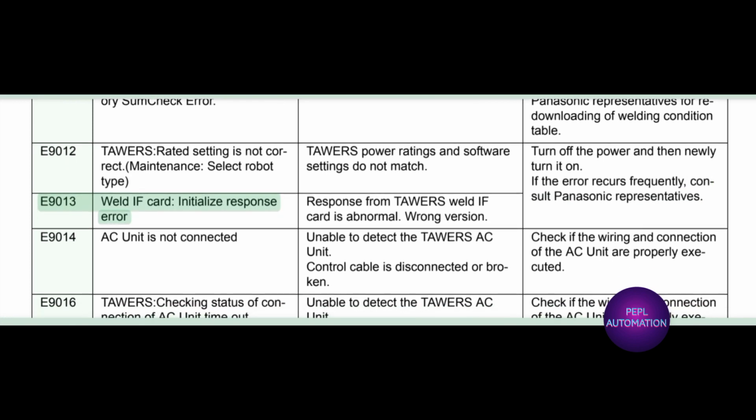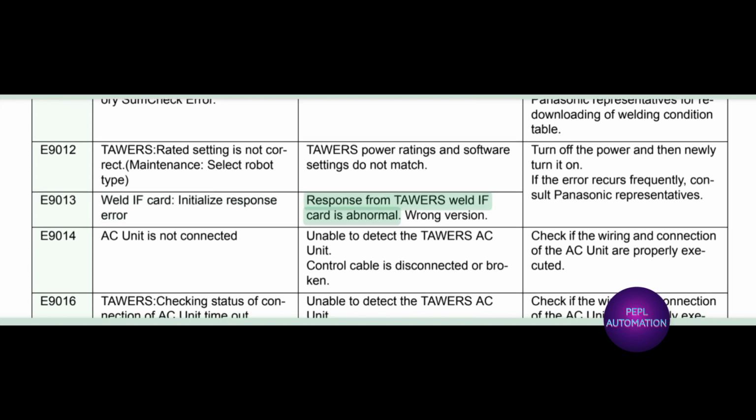E9013, welding card, initialize response error. Response from TAWERS welding card is abnormal. Wrong version.